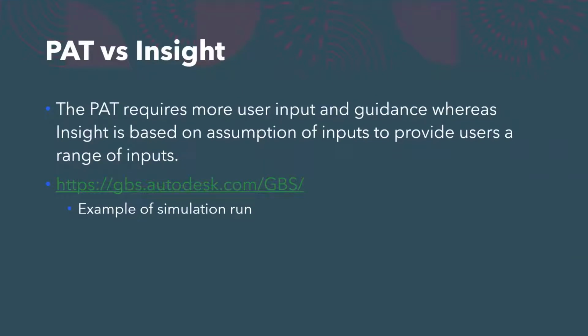So the manual mode is kind of a more watered down, simplified version. In my opinion, it is excellent to use in early design to perform what-if questions. Later on, I recommend just using the standard OpenStudio modeling process for optimization and sensitivity analysis.